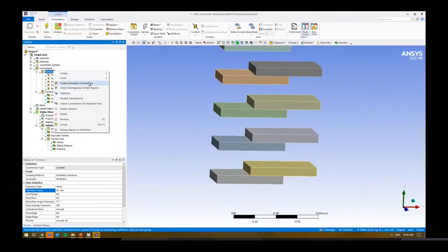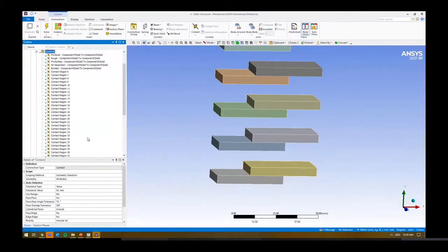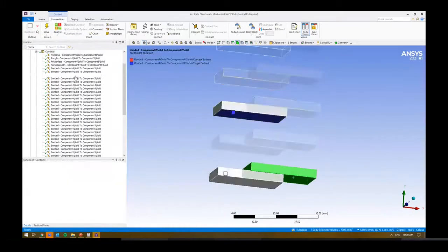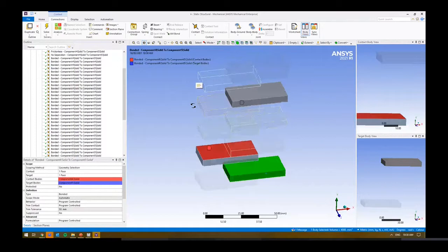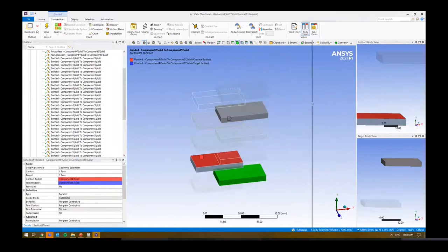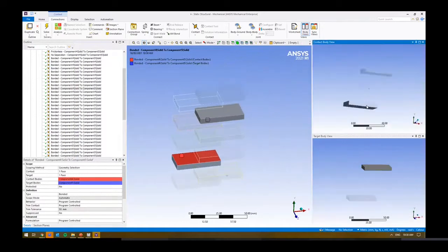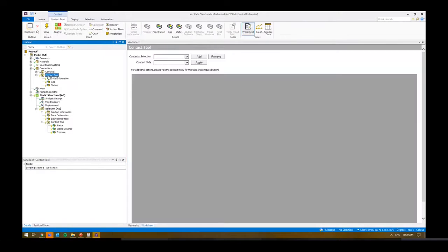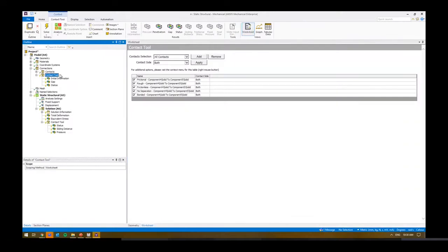I'm just going to force it to be bad. So I'm going to look for a 50 millimeter tolerance sizing. So it's looking at a surface 50 millimeters. And again, straight away you'll pick up, because of such a large component, even though these two things aren't interacting at all, it's picking up these two regions, right? So when you've got thousands of components, and we've got customers that have this, it can be very difficult to pick up what's happening here.